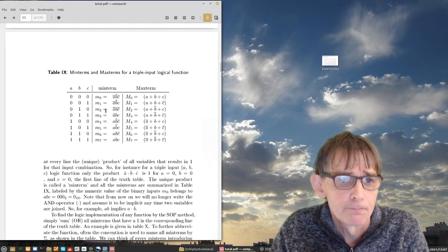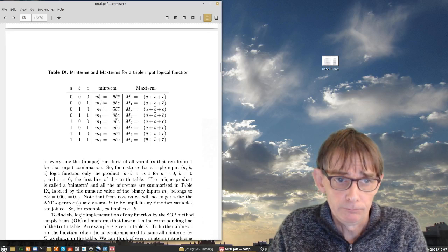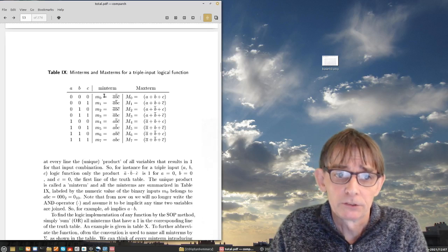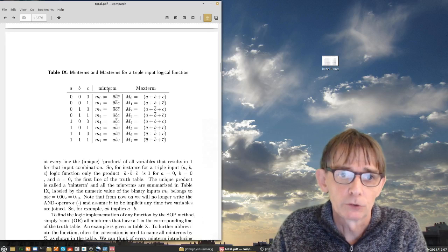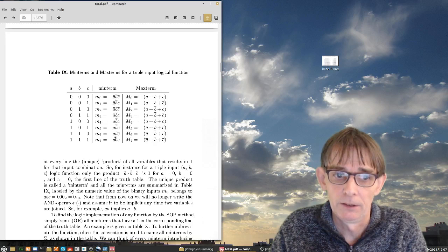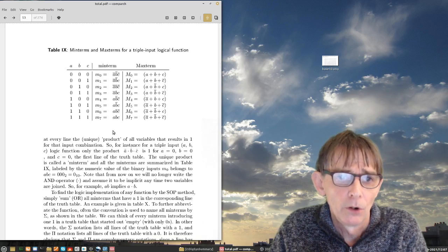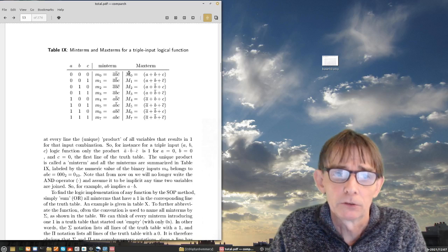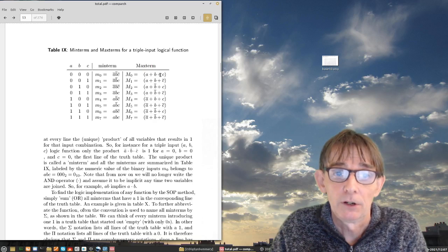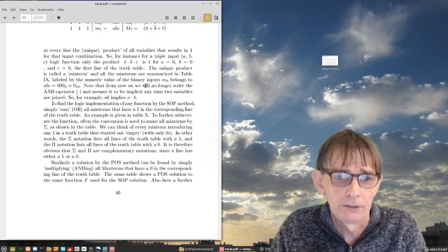And then for the sum of products operation, we just copy all the min terms, which are the associated products, and use them in a final OR operation. And if you want a product of sums, we take what are called the max terms, which are sums, and then take them in the final product, as you remember.